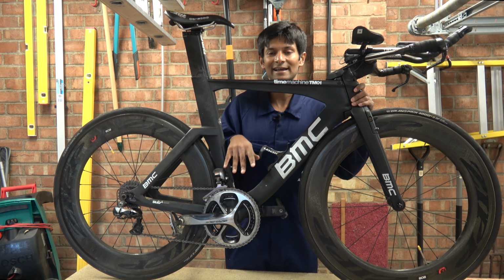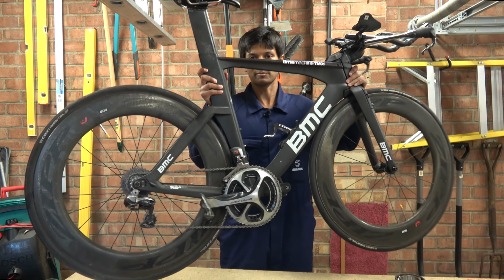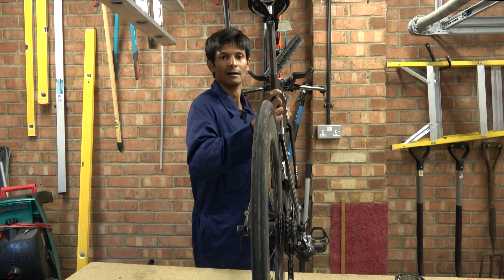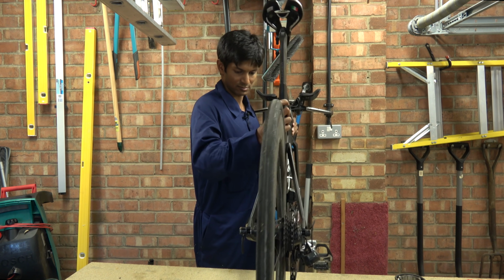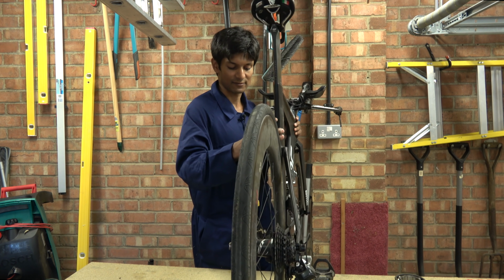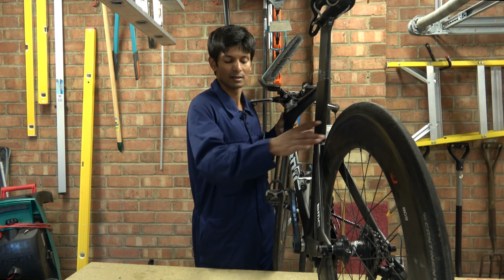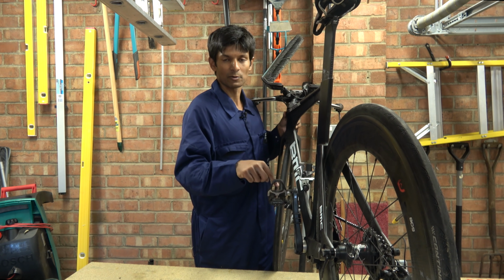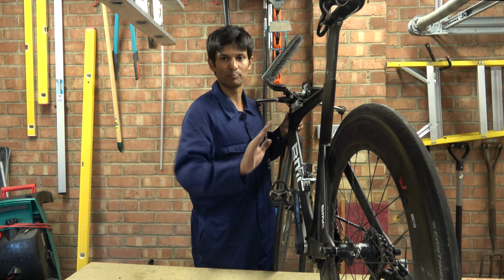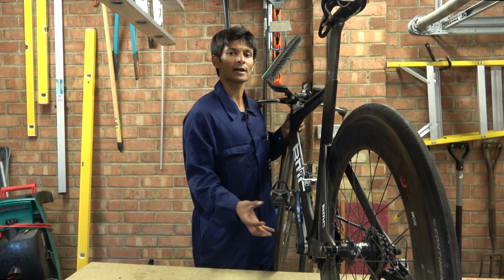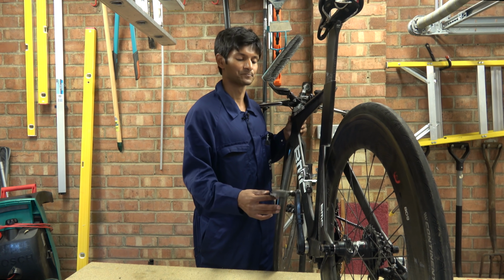The bottom bracket, again, if I was to turn the bike through, it won't fit. If I was to turn back, I don't know if that'll show up. The loading that you apply to the pedal gets bent through, so the bottom bracket is quite heavily loaded. So you've got a radial load and an axial load acting together.